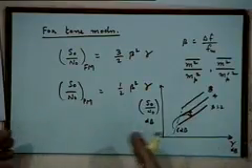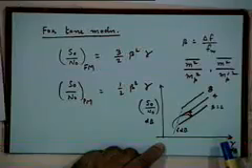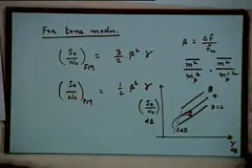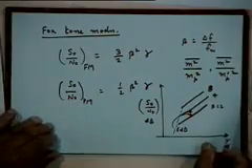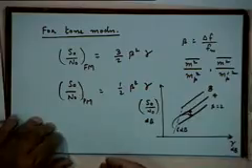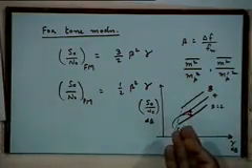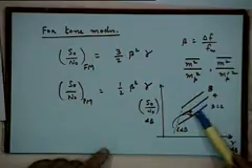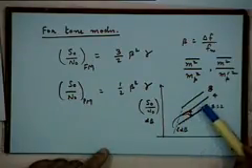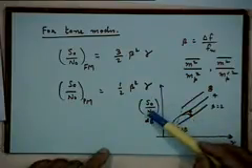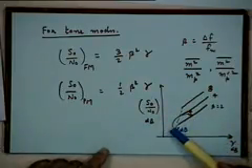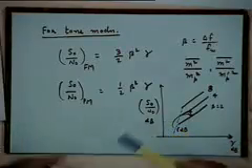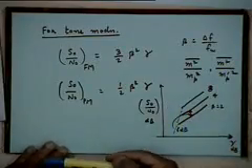Okay, and you get a very different situation in that as the noise increases or the input signal power decreases. Right? So let's look at that issue now, and that's the same issue which I discussed in the case of AM earlier, namely the threshold effect. That is, as the input signal to noise ratio decreases, unlike these straight line curves which imply a corresponding graceful degradation also of the output SNR, beyond a certain point the output SNR will decrease much more than the reduction in the input SNR.